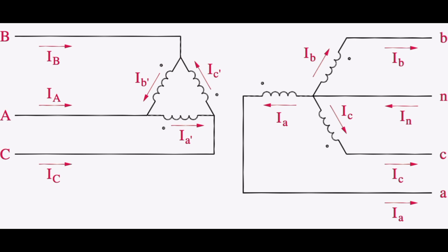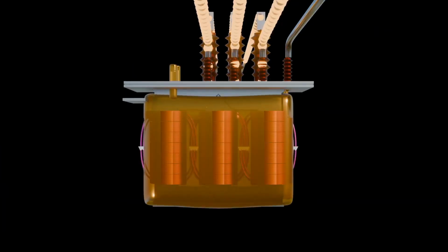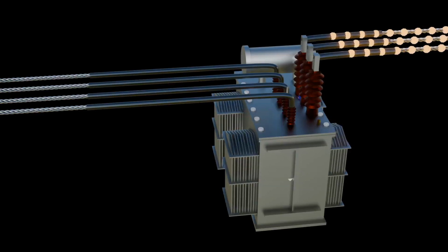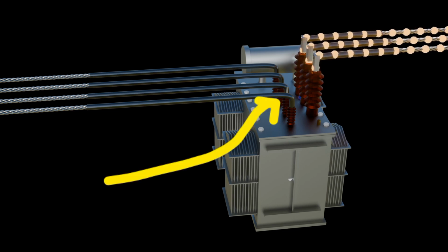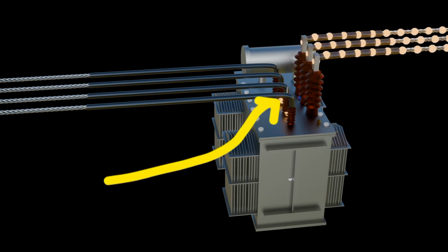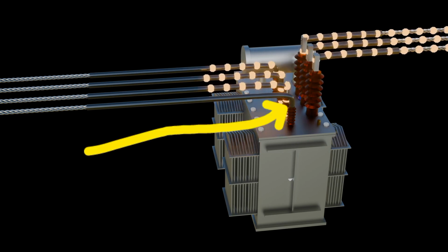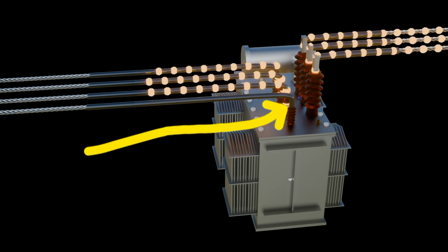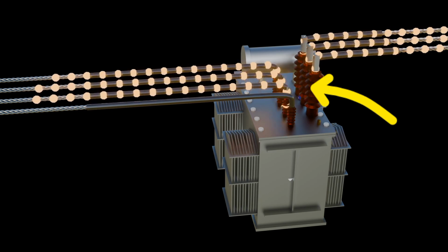Transformers suffer several losses through heat, be it eddy current losses or hysteresis losses, hence cooling oil is used, which sometimes expands, hence the use of a tank at the top. Also, bushings are used to lead current into and out of the transformer because of their good insulation. There are two categories of bushings in a transformer. For low voltage, they are called LV bushings, and for high voltage, they are called HV bushings.